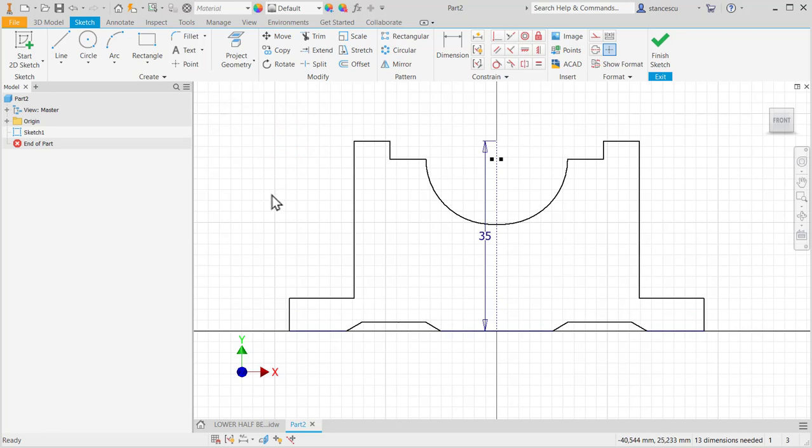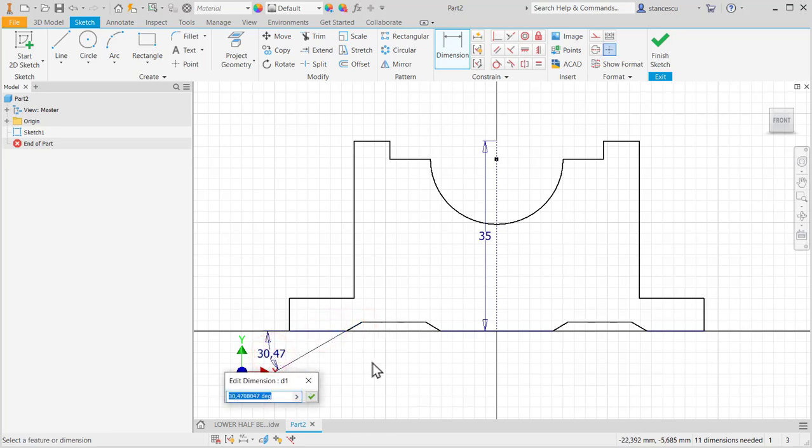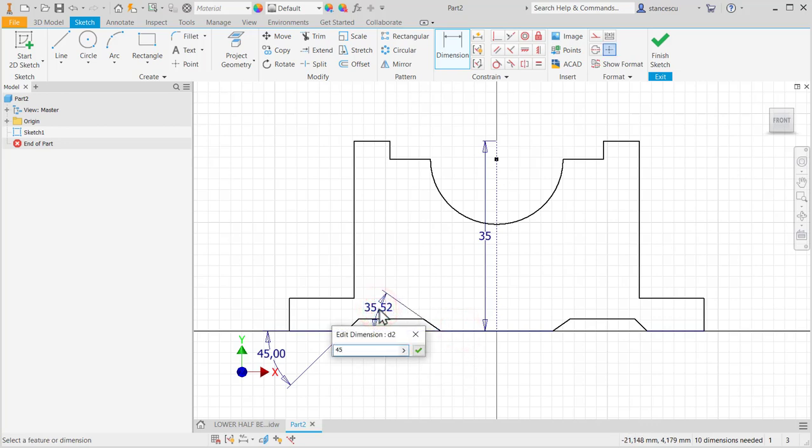Okay, now I'll place this point coincident, or on the same vertical, with this point, but now coincident. And now I'm sure that this is on the same vertical with the center point. You can explain to yourself why. Angles: the better behavior is to place angles first. 45.